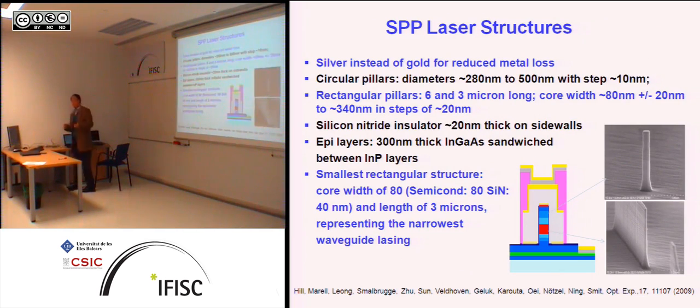Okay, so this is actually around 3-4 years back, when we were studying the feasibility of coating the semiconductor with metal, to see whether this is a realistic solution. We did a lot of simulations and thought this is feasible. We don't know whether it's exactly possible, but we thought it's at least not that crazy, so we should try it. So it's basically a semiconductor nanowire, let's say 200 nanometers, and we want to coat a layer of metal to make a metallic semiconductor cylindrical waveguide. So we tried to do that.